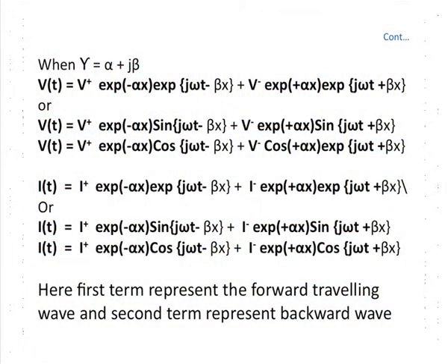When we put our propagation constant gamma as alpha plus j beta, then we can find the general solution. Each term will have exponential terms and sinusoidal terms. So, the exponential of minus alpha x will represent the decrement or attenuation of the signal when it propagates from the source to the end side, and the second is the sinusoidal signal, the oscillating wave that is moving in the direction of x here.